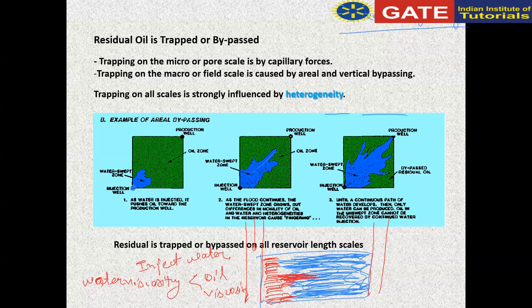That phenomenon is known as viscous fingering, because your injected fluid has lower viscosity than your reservoir fluid. So viscous fingering occurs. Got it?